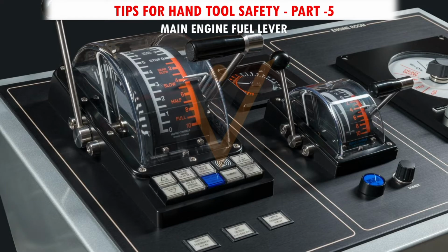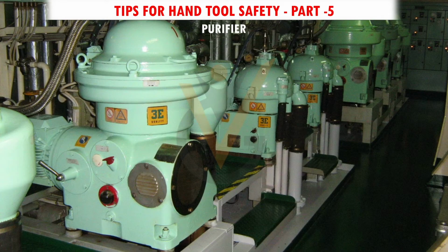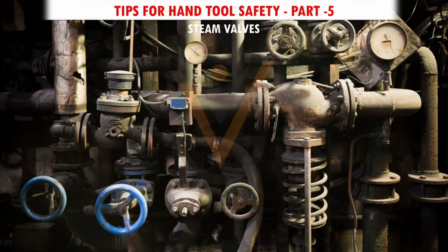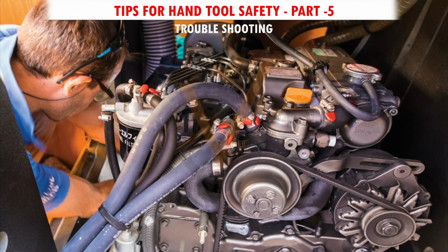If the main propulsion plant is running, bring the fuel lever to the 0 position. Close the feed of the running purifier to avoid overflow and wastage of fuel. If the auxiliary boiler was running, shut the main steam stop valve to maintain the steam pressure. Find out the problem and reason for the blackout and rectify the same.